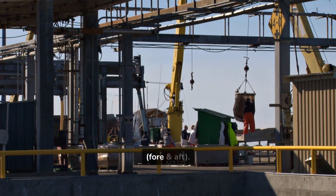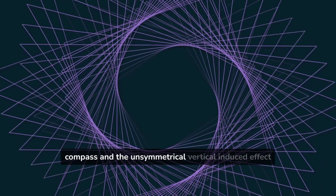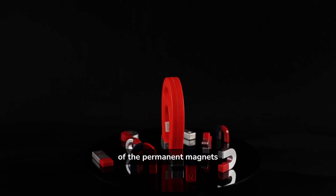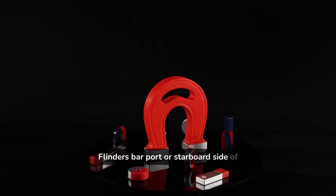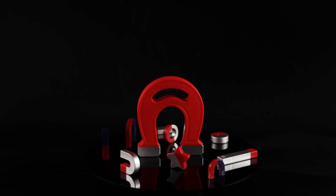The C error has two causes: the athwartship permanent magnetic field across the compass and the unsymmetrical vertical induced effect athwartship of the compass. The former is corrected by the use of the permanent magnets C, athwartship, and the latter with the Flinders bar port or starboard side of the compass, but this error is very rare. The C error is only corrected with the C magnets.